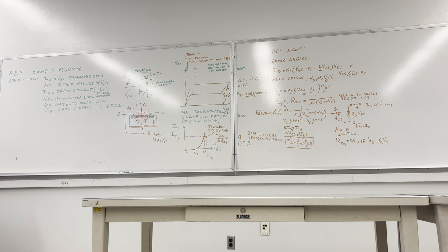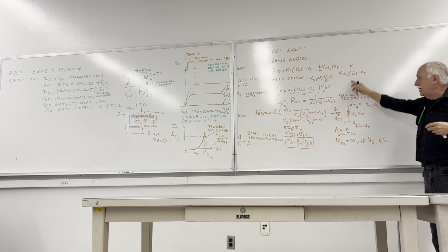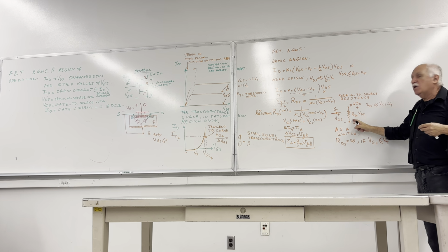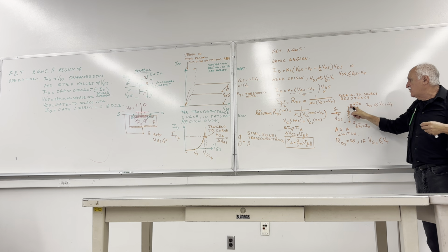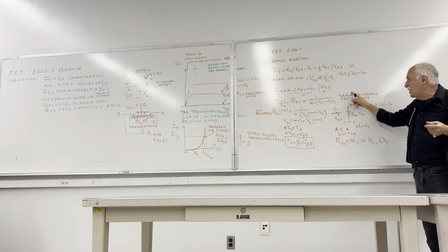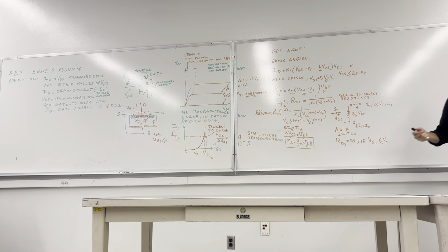So it is not that it's not going to get hot. It will, because when the current gets real high, even with a small resistance there, therefore a voltage drop, you have the I times V product, and there will be some kind of power dissipation in the transistor. Though small, but it will be.